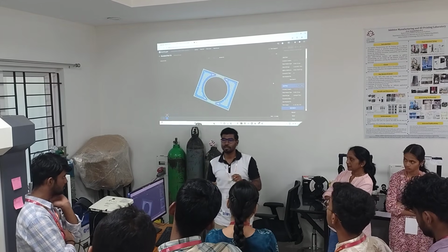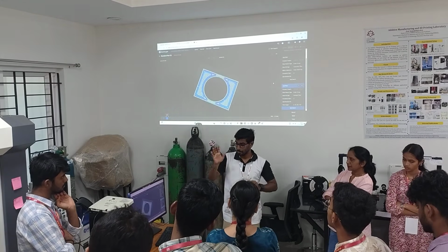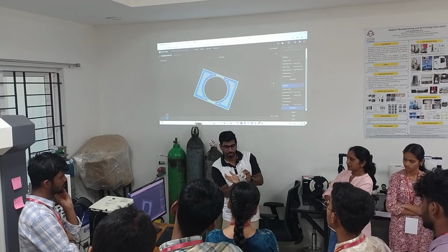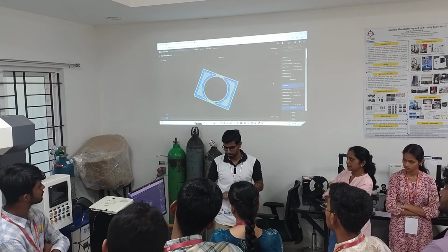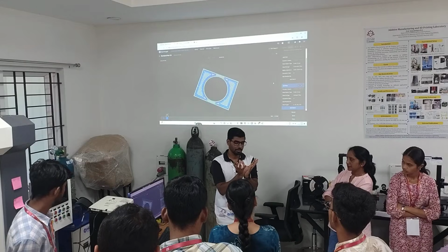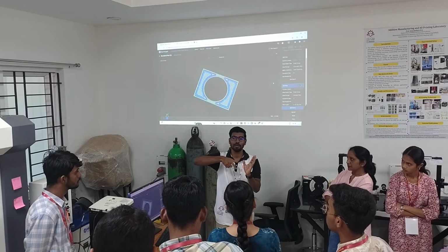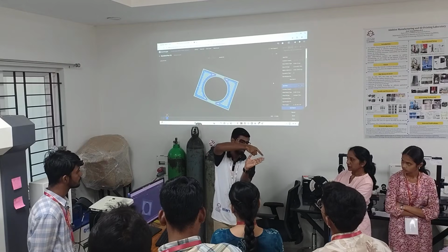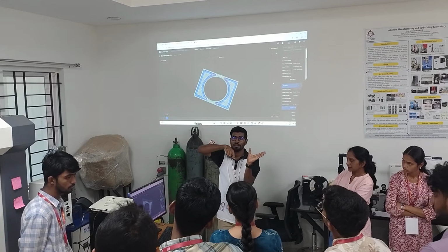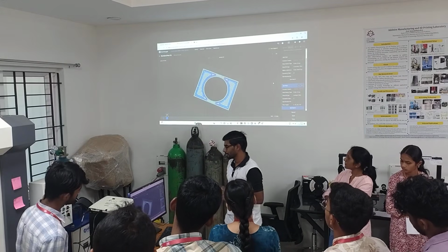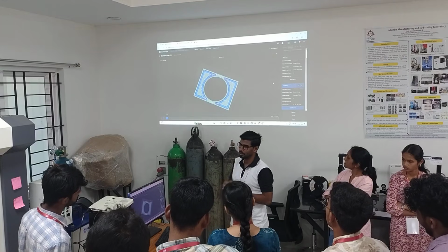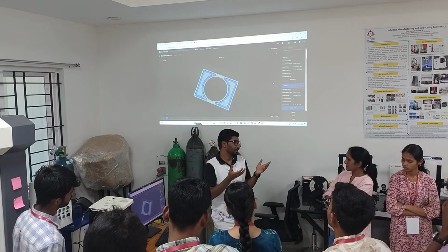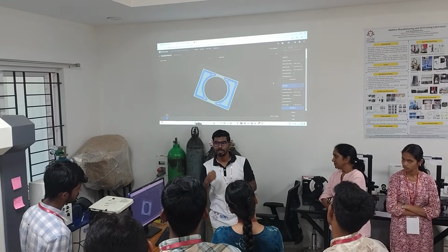So this is one of the disadvantages of additive manufacturing of composite fiber, specifically in this machine, that if you have a curved path, just like a glass or something, it will not be possible to have it along the walls. Even if you place it like this, only some of the layers will have it, and then it will not be continuous along. So additive manufacturing of composite is still in progress and people are trying to improve it. But the same thing can be done with a very small amount at the layer level.